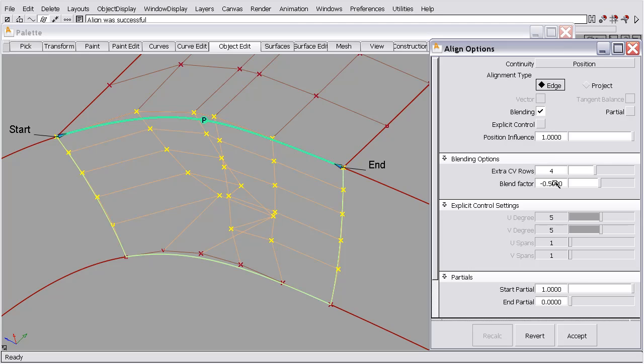So we can add extra movement in. Now, it may look like you never want that, but sometimes that can be useful. So 0 is equal movement. Negative numbers are movement equal to plus additional movement, and 1 is taper. 95% of the time I have this set to 1, but just so you can see, if you Alt key and slide in here, you can modify those numbers a little bit.